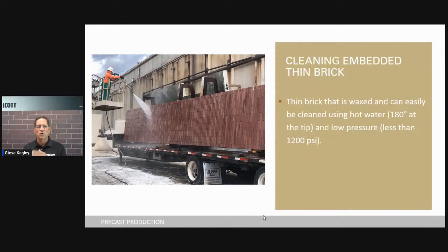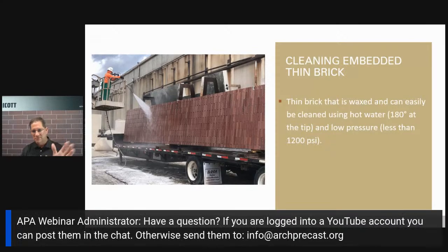You're using a lot more sand coated brick today than we used to use. So you don't want to cut into that and get into the body of the brick. You also want to make sure that wall is just saturated with water, just good, clean water that's not got all kinds of trash and impurities in it. You've got to start at the top, and keep a 4 or 5 foot section, and work it all the way down to the bottom with clean water. You can't just go back and forth and let it dry and things like that.